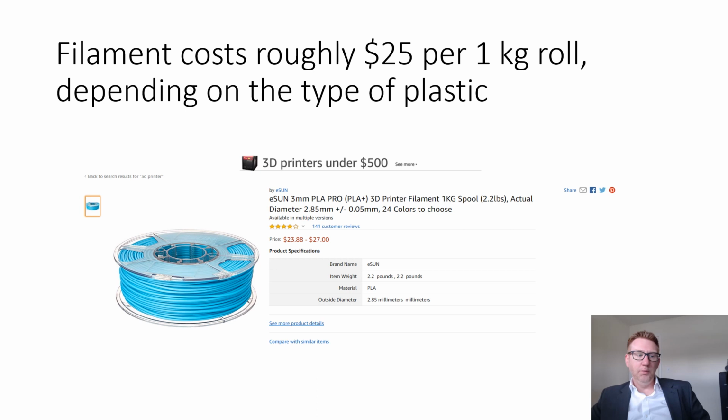A lot of the models that we make, by the way, are not printed in solid form. They're printed with what's called an infill. So the interior structure of these objects tends to be semi-hollow. There's sort of a grid that the slicer puts in as it carves the model up, and it basically builds support structures as it goes. So the models that you print are rarely solid plastic, although you can choose to do that if you want. They're usually printed with a 20% fill or a 30% fill, which is still fairly strong, but saves on a lot of print expenses.